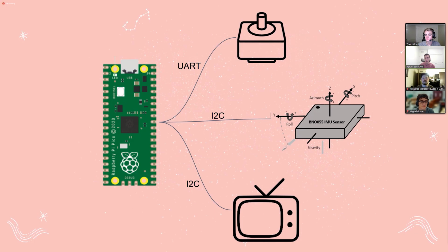The Pico is also connected to a 9-axis IMU that gives us our current orientation. We can get our roll, pitch, and yaw and convert those to equatorial coordinates when we are saluting the stars or tracking. Finally, we interface with a little OLED screen that can display information to the user during polar alignment and other helpful information throughout the operation of the mount that doesn't make sense to display in the app.